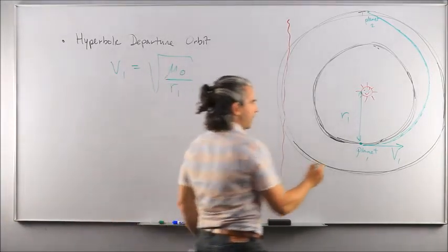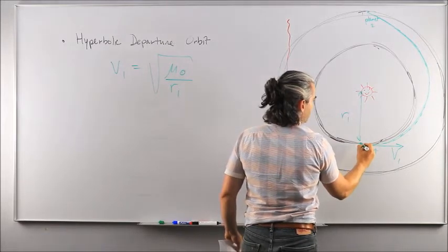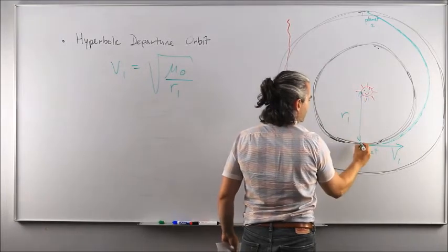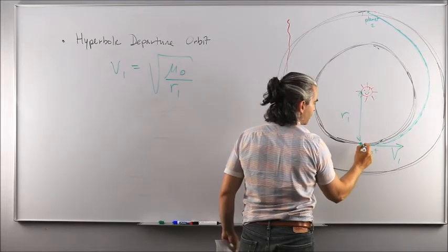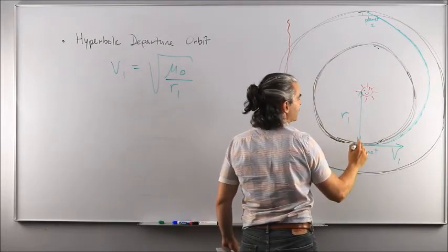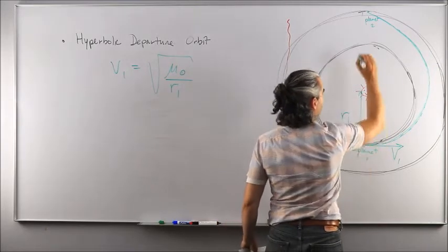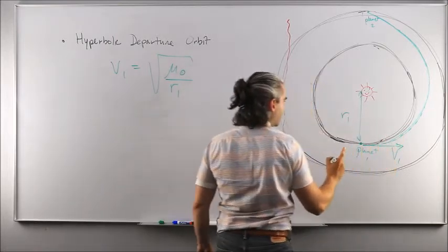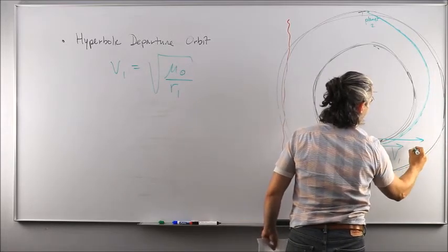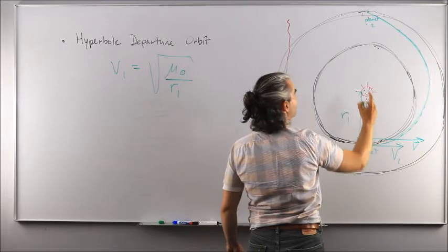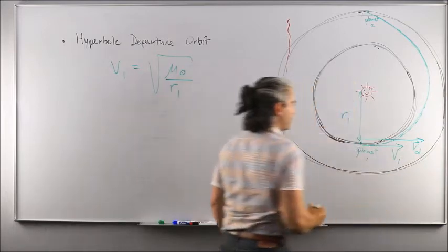But if the spacecraft is orbiting here around the planet, we will assume that from that perspective, the spacecraft has the same amount of speed as the planet, okay? So it's kind of stuck together, orbiting around. But from this grand scheme of things, we're assuming that the spacecraft has the same speed. But that's not enough to go from here to here, because what we want is to have a larger velocity that's going to correspond to the speed along this transfer orbit at its perigee. And this is going to be denoted by VD.